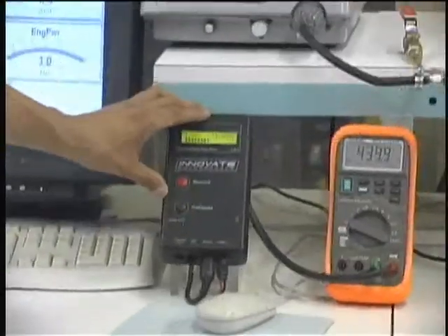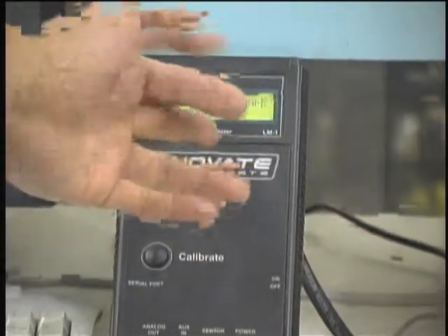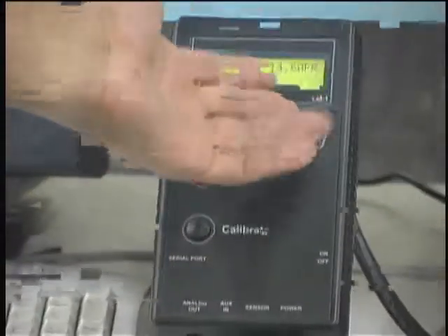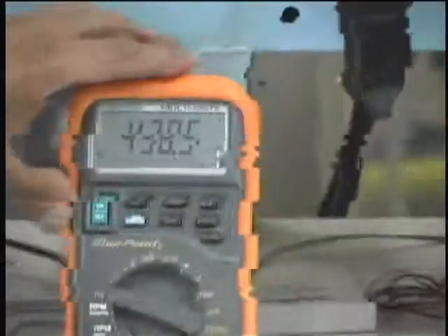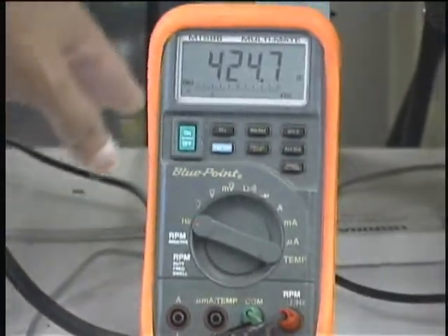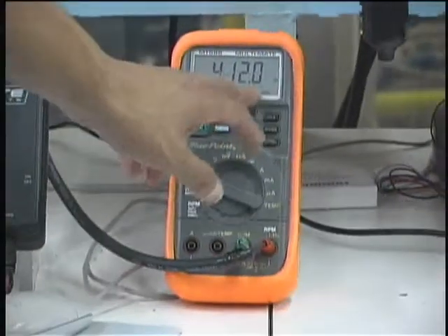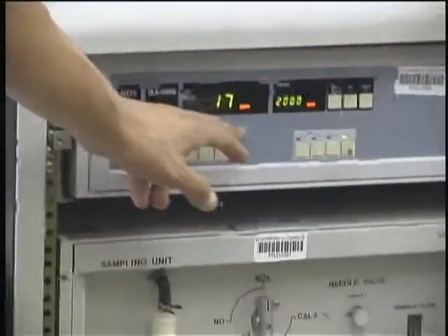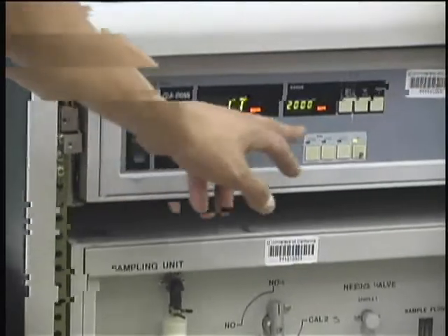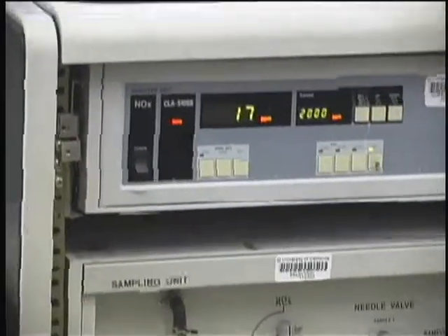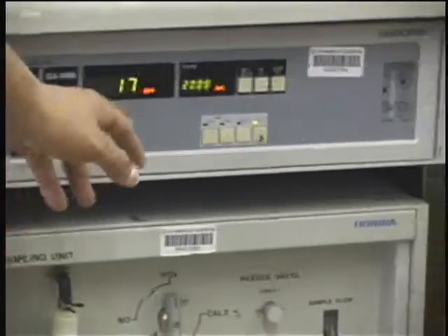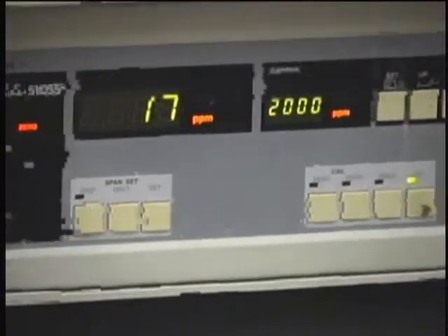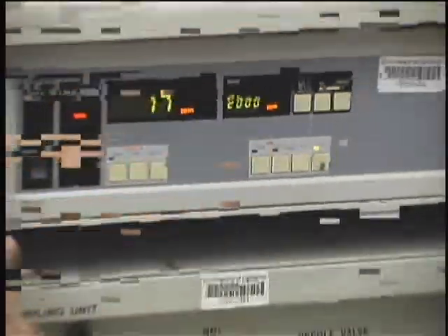This is your lambda meter. You would take the number to the right. Right now the air-to-fuel ratio is 14.7. That's what you want, 14.7, the one on the right. This one is your M.H2O meter, your turbine flow meter for the water flow rate. It's in hertz. Over here is your NOx in parts per million. You would write down the number 17. This 2000 just means that's the maximum range this machine can handle. Anytime you see the word over, you write the word over on your data sheet. It means it went over the maximum range, which is 2000.